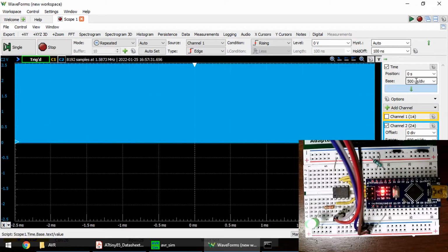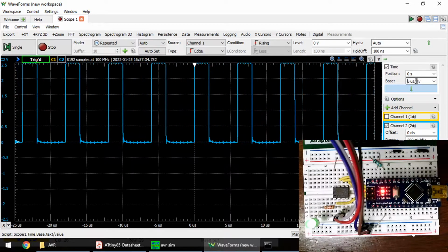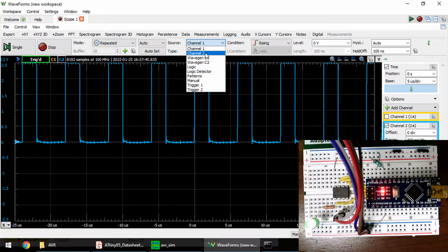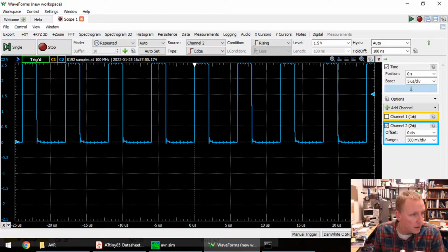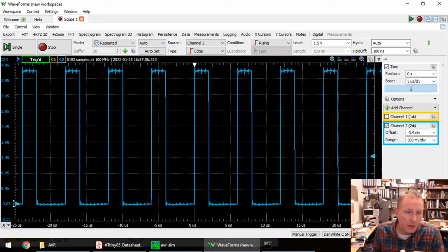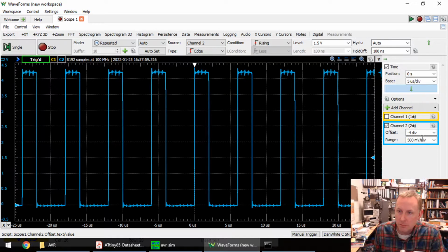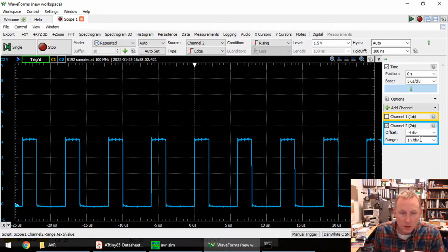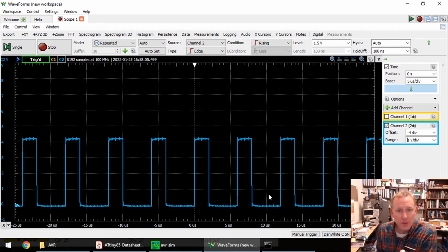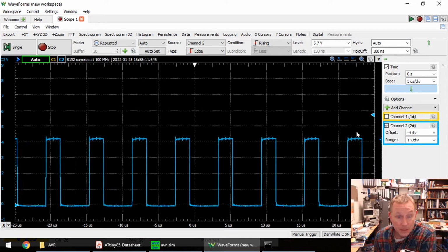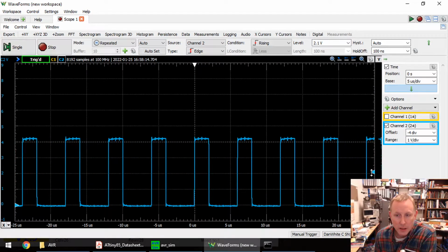Remember, I'm toggling this really fast. I need to zoom in. Doesn't look so good. Well, actually it looks better than you might expect. My signal's actually on channel 2. I'm going to trigger on channel 2, put this way up here. Okay, scroll down so I can see this. All right, you can totally see that this is not 50% duty cycle. Look on the right side, move my trigger off of here, and it's going all over the place. That's the whole idea of trigger.